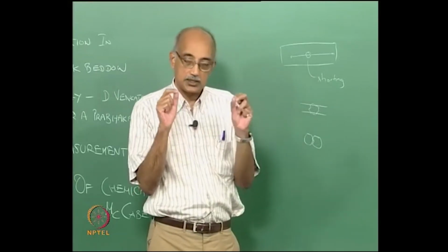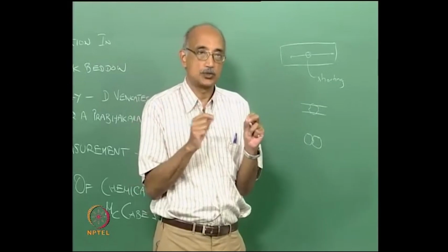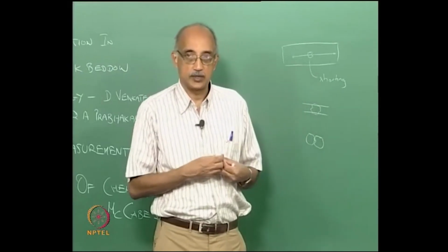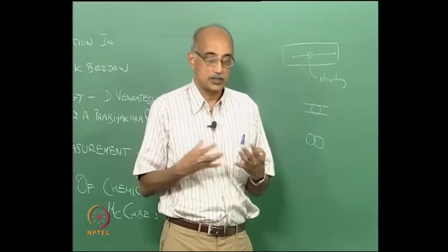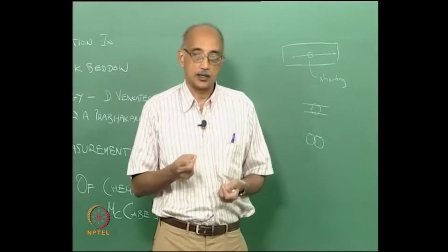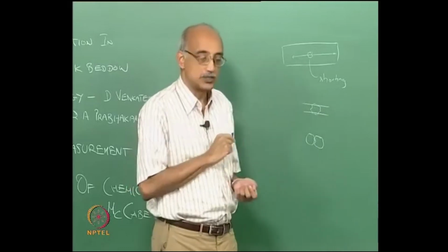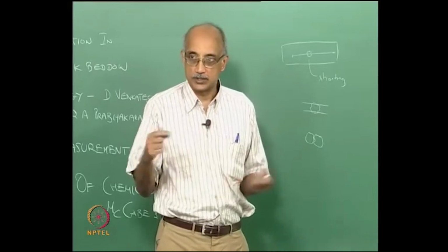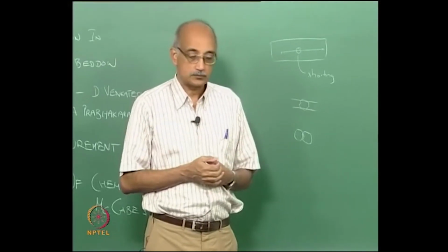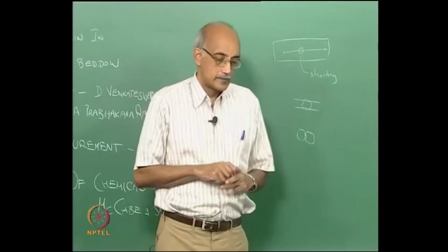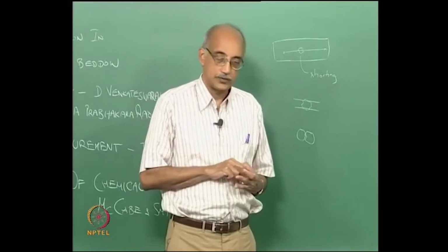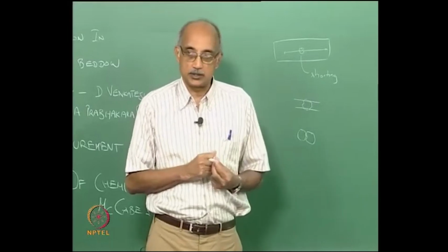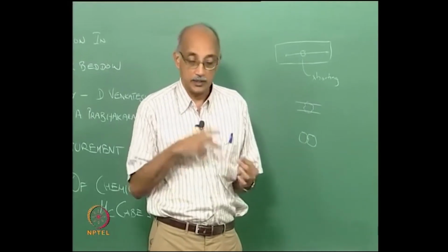When particles are discrete, the suspension acts like a Newtonian fluid. When the particles start coagulating, it starts to behave like a non-Newtonian fluid. So, there is a tremendous difference in the flowability characteristics of any suspension depending on whether the particles stay isolated or whether they start conglomerating. So, clearly adhesion of particles to surfaces and to each other is of huge practical significance, and it is worth studying it in more detail.